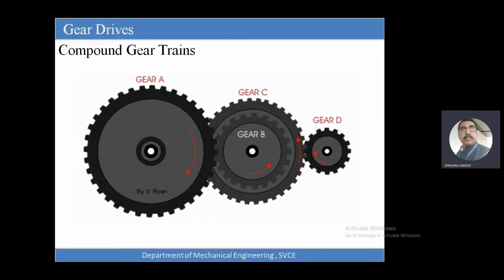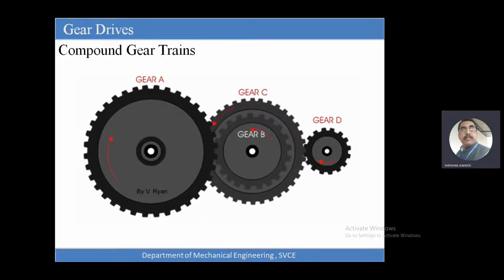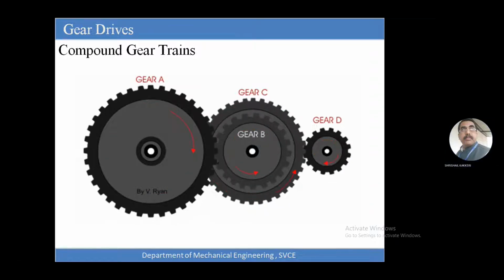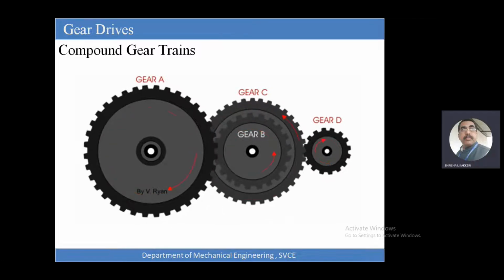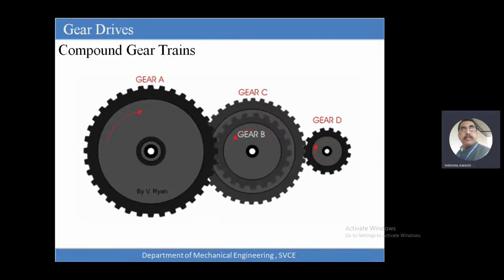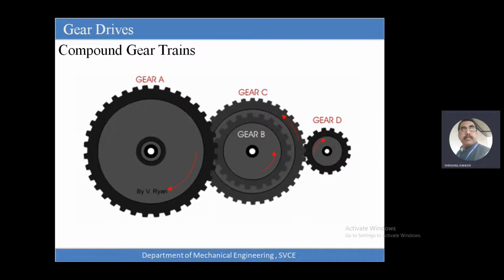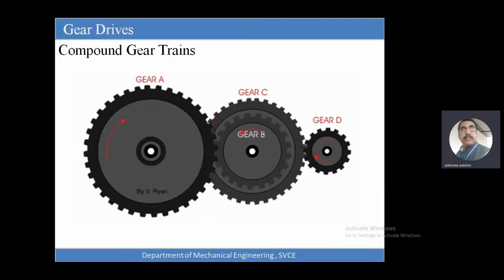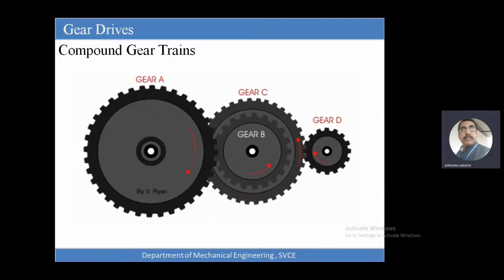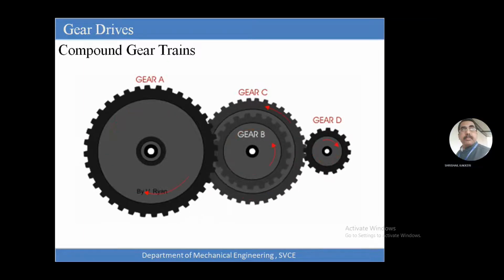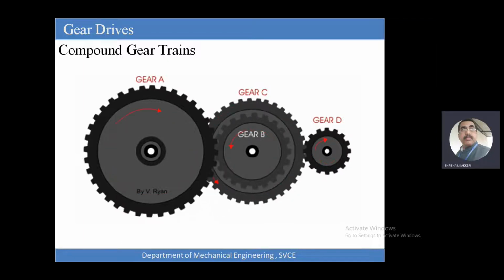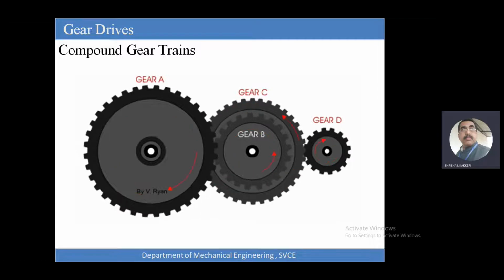Now, one should have a small idea about how the rotation will happen. In the examination, they will give us gears, say 3 gears, 1, 2, 3 respectively. The number of teeth of gear 1 will be 30, on this 40, on this 50. The speed of the driver gear is 1200 RPM. Find out the speed of the driven gear and its direction, they will ask us.